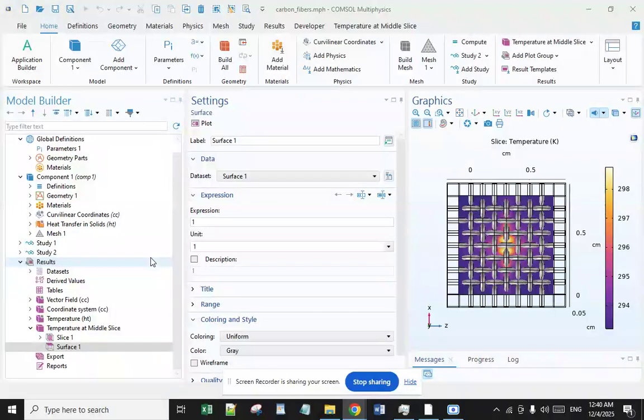Heat transfer plays an important role in all stages of composite manufacturing. Heating in preforming is used to melt the thermoplastic matrix or binder so the fabric can be deformed and the layers consolidated, and also to cure the adhesive binder for thermosetting binders. Preforming takes place in single diaphragm forming (SDF), double diaphragm forming (DDF), or matched tool forming.